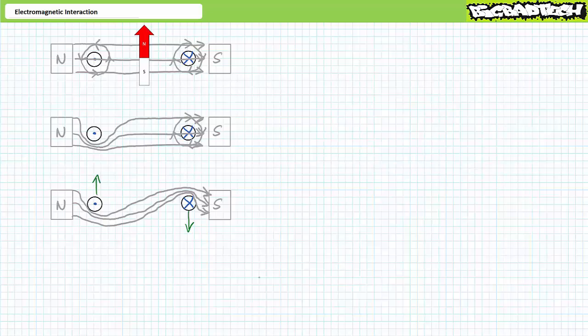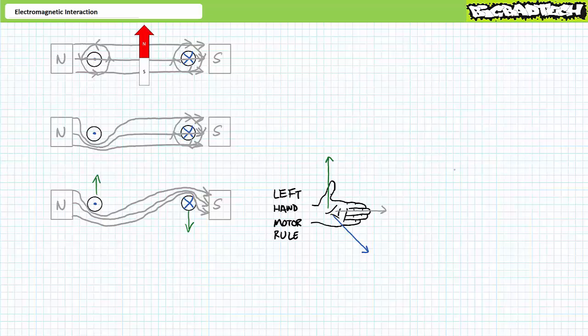Given the left and right conductors are in fact cross-sections of the same three-dimensional coil, this coil will be torqued clockwise as the magnetic fields seek alignment. While it is entirely possible to explain this interaction using our previous understanding of current magnetism, it can be more succinctly explained using Fleming's left-hand motor rule,